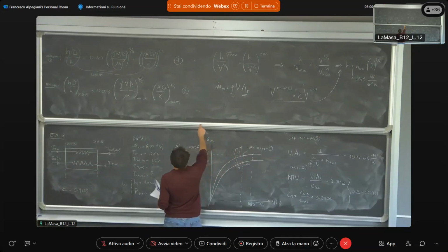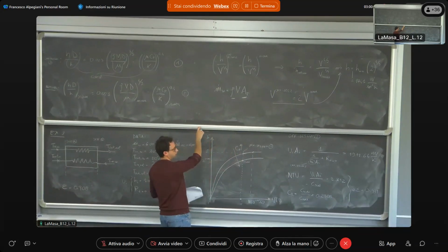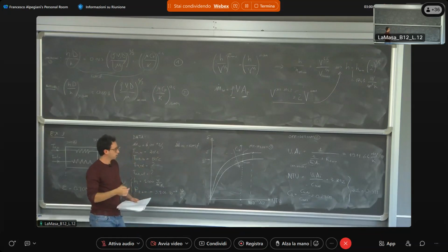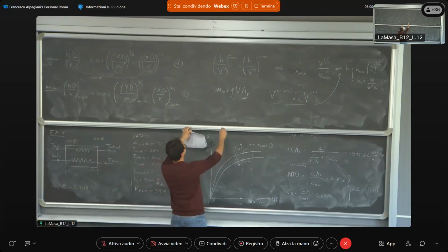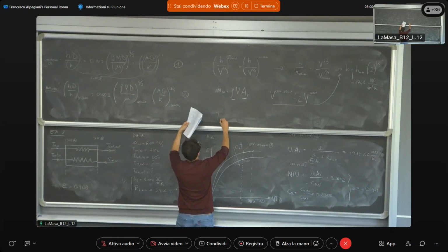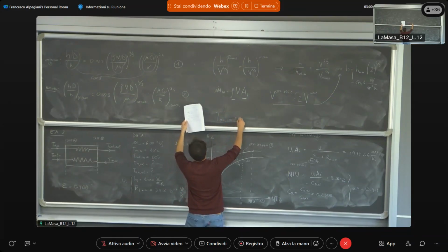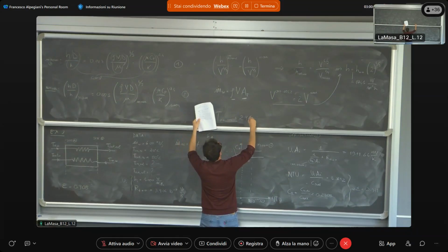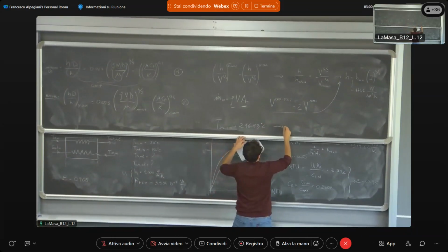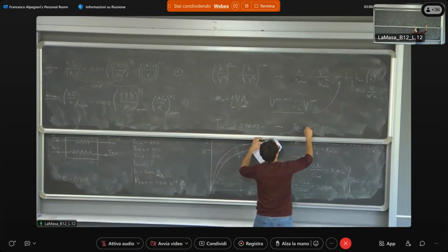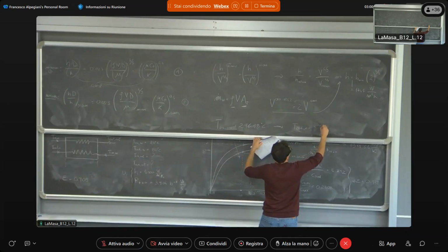I don't have anymore here the three heat balances that I've written before, but exploiting the same procedure that we used for the off-design number 1, we can evaluate the temperature for the T oil at the inlet, which comes equal to 296.98 degrees Celsius, and then with this you can evaluate also T out of the oil, which comes equal to 336.98 degrees Celsius.